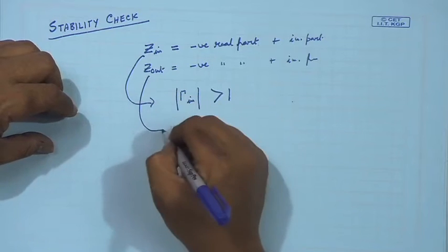Now, in the normal Smith chart that we use, we consider all of them as passive impedances. So there the real part is never negative, real part of any impedance is never negative, it is 0 to infinity, any value it goes. So when Zin has a negative real part, basically the point goes out of our normal unit circle Smith chart, and that time gamma in becomes greater than 1.